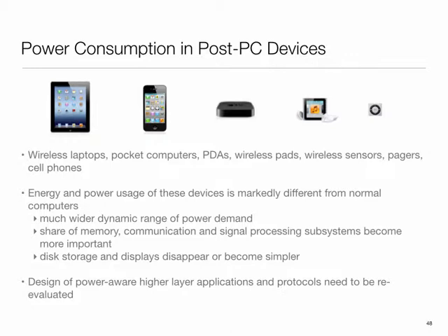Okay, so it's light emitting, it's a projector. Well, our OLEDs and LCDs are also emitting light, so that part is still there. Anthony? Is it higher because it has to be able to work outside in sunlight? Okay, so it has to be bright. That's one part, but there's also the issue of optical loss, because it's no longer on a surface. It is being projected up in the air, so with the distance to that image, there's going to be a d squared loss.